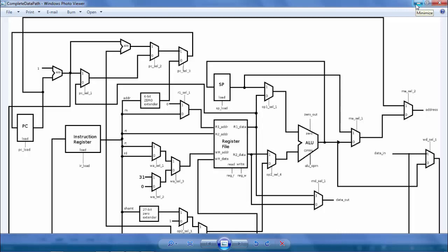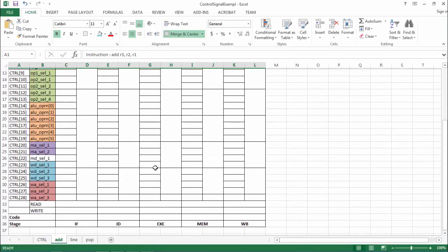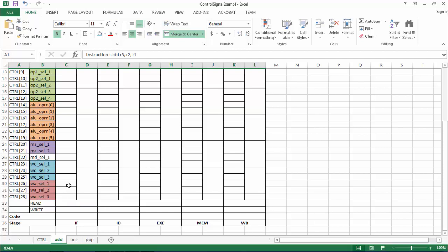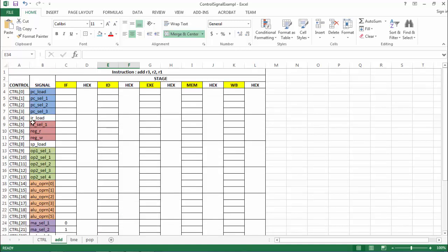So for this instruction fetch, what we need to do is put memory address selection 2 as 1, this is a 0, and then we need to make sure we are reading from the memory. So 1 0. Now let's assume at this point 0 0 is a hold for my memory and also for the register file.